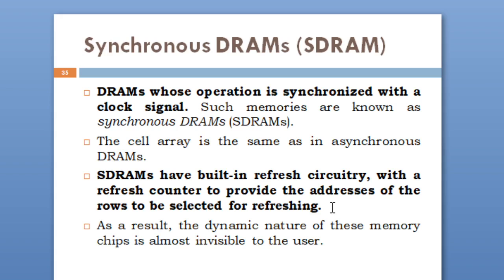As a result, the dynamic nature of these memory chips is almost invisible to the user. So these refreshing activities will not be visible to the user. That will be done by using this refresh circuitry for every 64 milliseconds, so the selected rows will be refreshed.